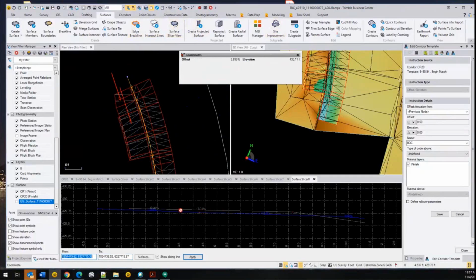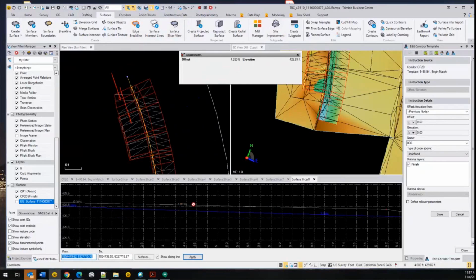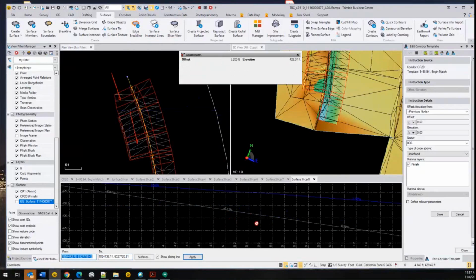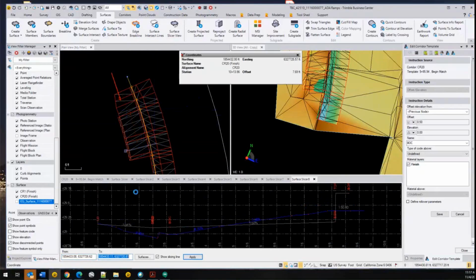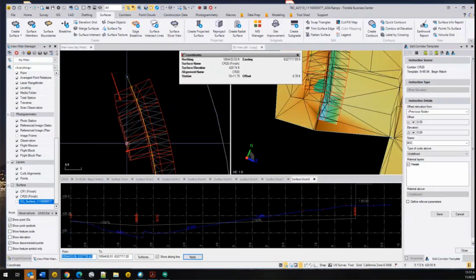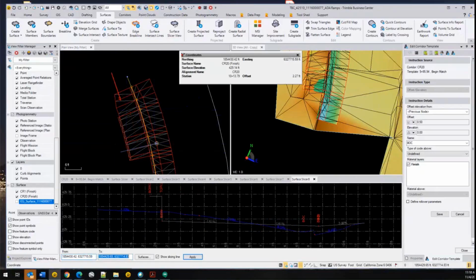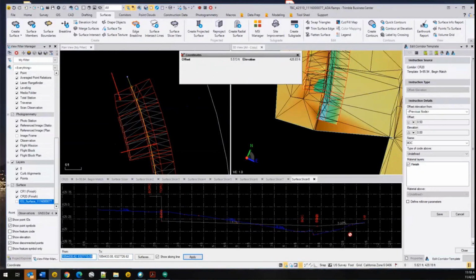And we're dealing with a 1%, so it's the gray slope here, 1% on the sidewalk. And then if I go down our ramp, it looks like 6.8 to 6.9% on our ramp, which I believe is good. If we go cross up through here, I'll draw it so that it's looking the same way. We have 1.5% here and 3% from the lip. I believe that's okay.